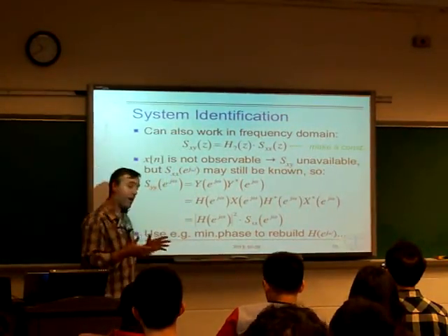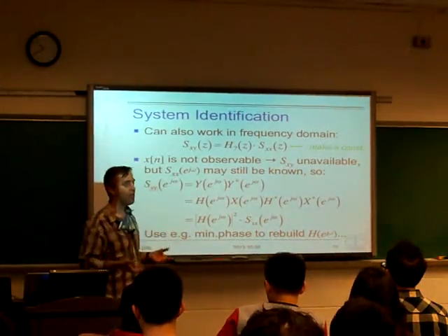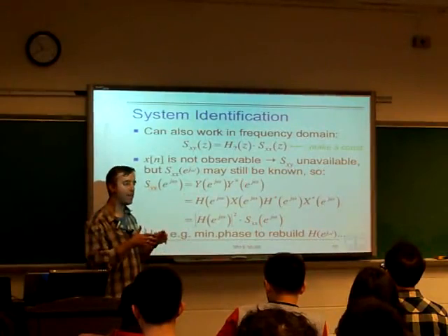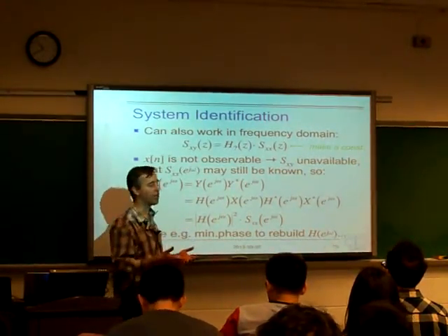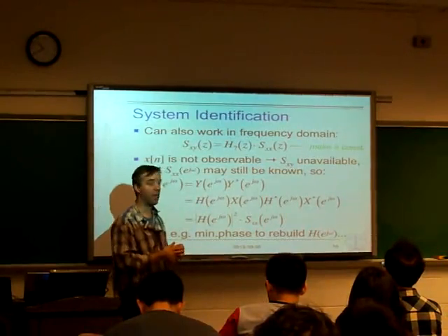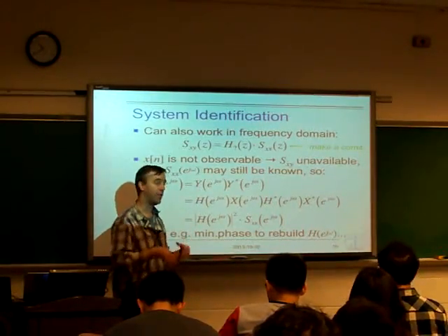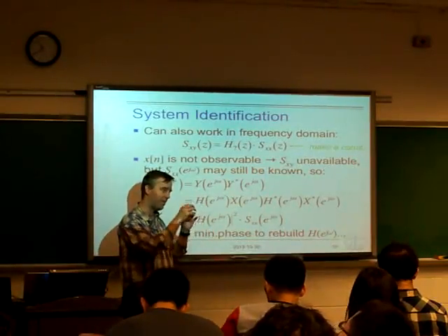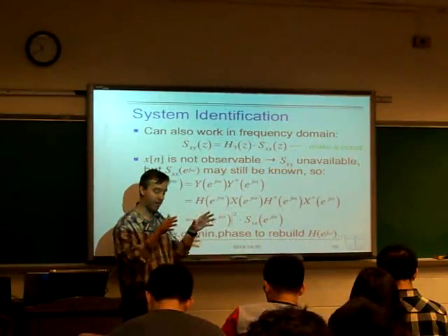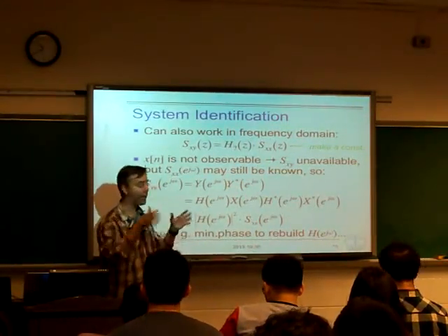But we may know something about the general properties of the input. We may know that, taken over a long time, it has an autocorrelation structure that's stable. This is a very common situation for a signal, which basically means we know its average spectrum. We know on average how much energy it has at different frequencies, but a particular sample will have some variation in those energies and some unknown phase relationship. But if we look over long enough, then we know that the total energy is going to average out.